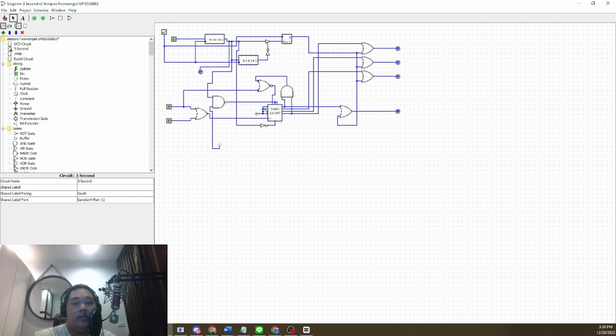The first shifter is connected to the clear input of the 74161 counters to facilitate this. An inverter is introduced to convert the active high signal to an active low signal. For clearing purposes, an additional NAND gate here is incorporated to act as a safeguard, preventing the inadvertent introduction of more numbers into the circuit.